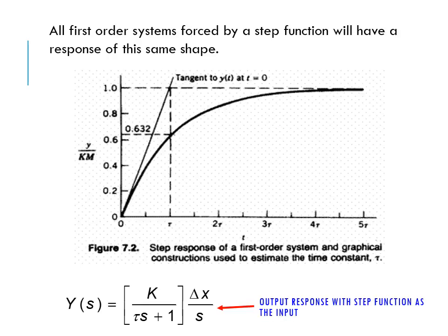The response of a first order system is monotonic. What we know as monotonic is this kind of process response curve that is stable if its time constant is positive. So to find the time constant, as I explained before, it is at 63.2% of the x-axis.